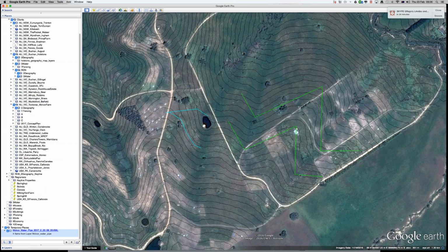Sometimes, now just bear this in mind, sometimes there is a difference in projection between the two, and you need to be aware of that. There's not much you can do there that I've found, apart from really tightening up on the geographic projection of the two maps that you're working with. You're working two bits of software, even though they might be using the same projection system. Like here, this is in Universal Transverse Mercator.